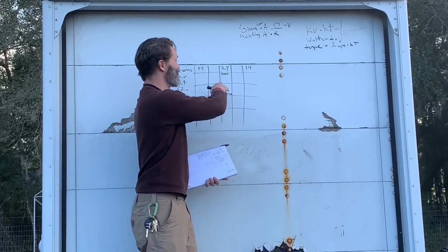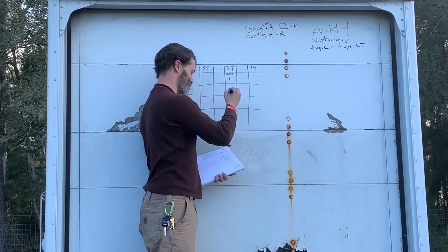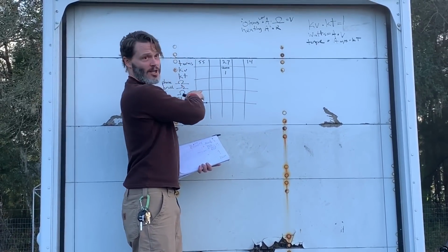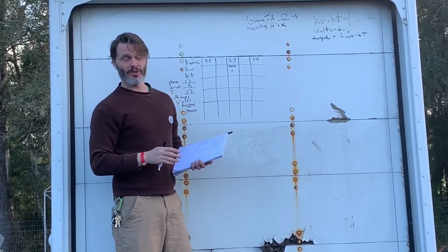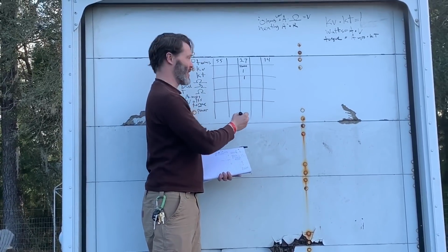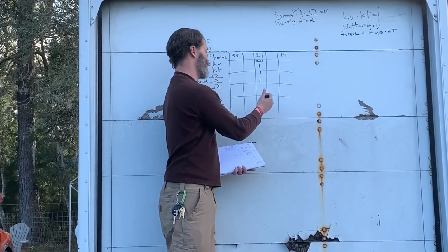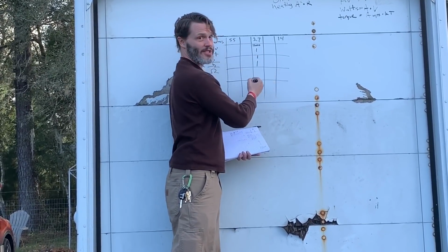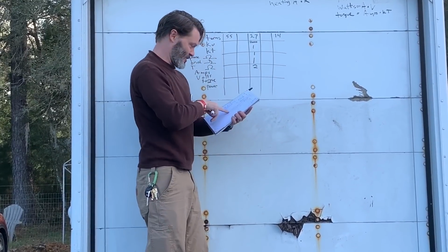So I'm going to say that the KT, the torque constant for this one, is going to be equal to 1. Our phase ohms, the resistance of the coils inside the motor, we're going to go easy today and assume that the ohms are 1. The brush resistance, again, I'm going easy today, so ohms of 1. Our total ohms for our motor now, we can deduce, 1 plus 1 is 2. Maybe you follow me. Now, let's go through my chart.